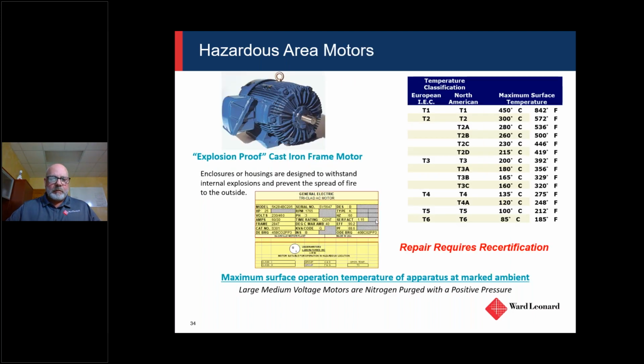And this is a little bit more about hazardous location motors and what the temperature design is. They really are required to meet a certain temperature design too, right? So if you have UL applications and you need help understanding what those are, or even if you have a UL motor in there and you maybe want to derate or declassify that UL area, because I'm sure there's insurance exposure to those as well, we can help you with that too. We can help you understand if you really need to have a UL motor in there or not. It may not be necessary, or it might be.